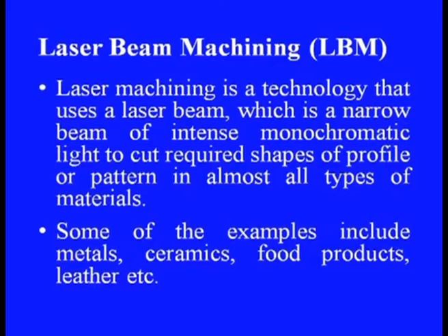Laser beam machining is a technology that uses a laser beam, which is a narrow beam of intense monochromatic light, to cut required shapes of profile or pattern in almost all types of materials. This is another striking feature of laser beam machining, that this particular process can be used to process any material irrespective of its hardness, irrespective of its melting point.